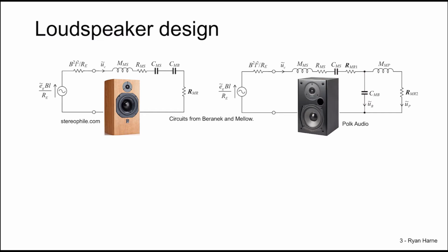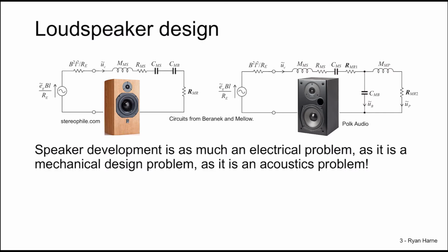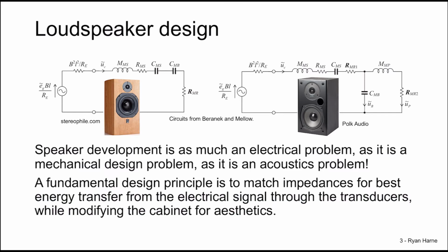Loudspeaker design nowadays is highly electrical. It's due to the fact that there are electrical mathematical analogs for mechanics and mechanical design, as well as for acoustics, so speaker development is as much of an electrical problem as it is a mechanical design problem as it is an acoustics problem. The fundamental principle, though, and especially since the design is handled in an electrical domain, the fundamental principle is to match impedances.